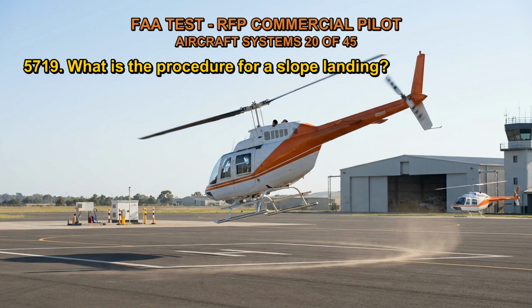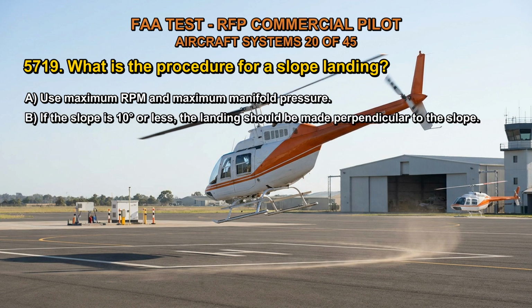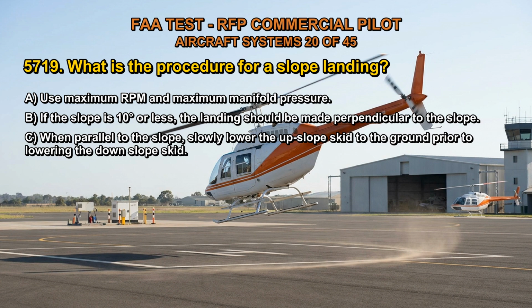5719. What is the procedure for a slope landing? A. Use maximum RPM and maximum manifold pressure. B. If the slope is 10 degrees or less, the landing should be made perpendicular to the slope. C. When parallel to the slope, slowly lower the upslope skid to the ground prior to lowering the downslope skid.